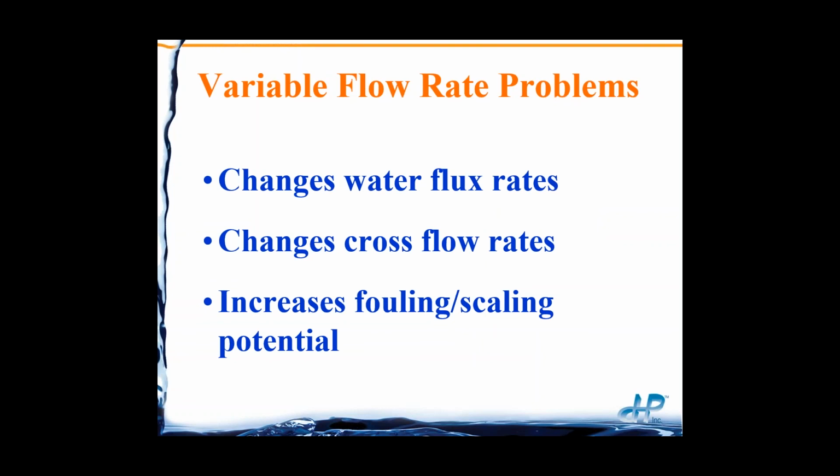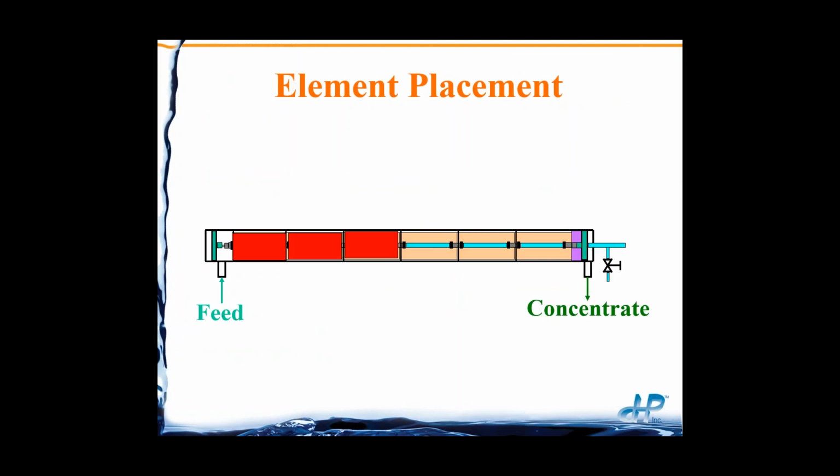A little thing like this: you've got a high pressure drop across the first stage of your vessels. You don't really know how many of these elements are in bad shape unless you take them out and weigh them or do something to determine which ones are highly fouled.